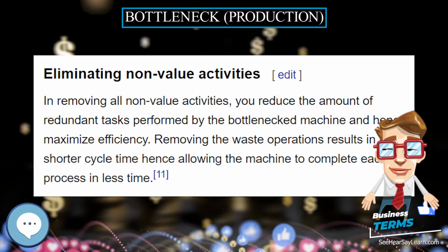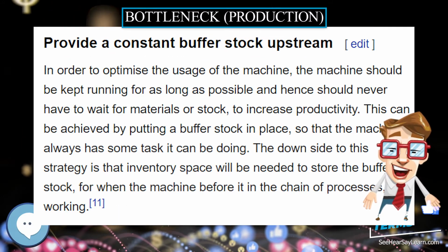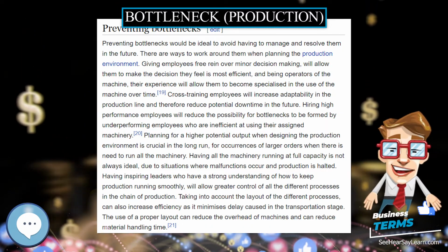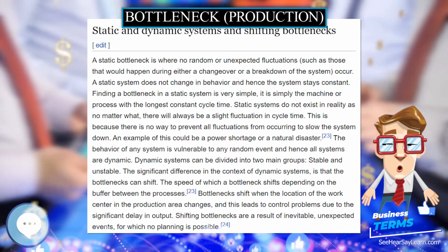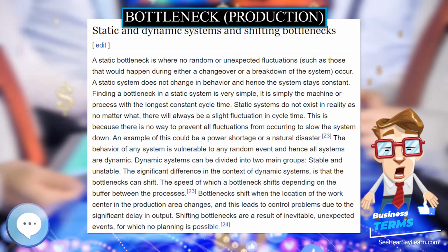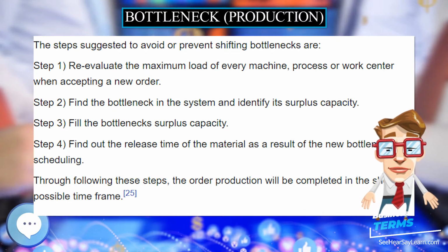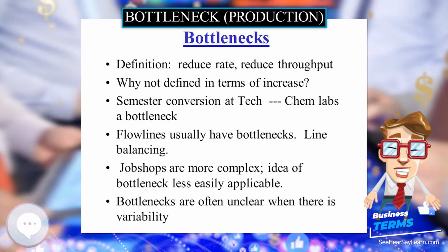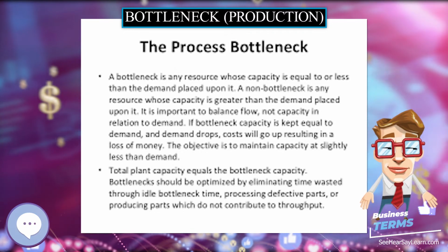Fishbone diagram. A fishbone diagram is a graphical means for finding possible problems in a chain of processes. By collecting the different data related to the problem, and inputting them into the diagram, it becomes easier to analyze the data in the order it is used, and hence determine the root of the problem. This is commonly used to find the bottleneck in a chain of processes due to being able to pinpoint the machine precisely responsible for the delay in production.